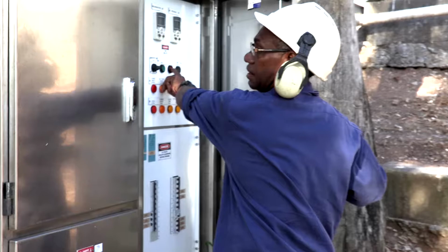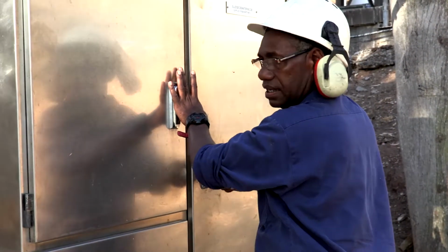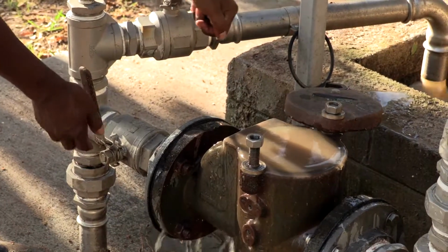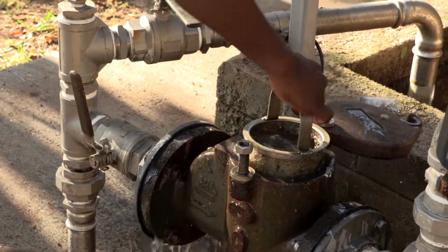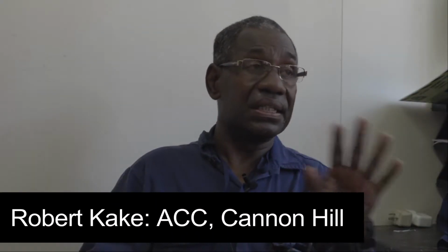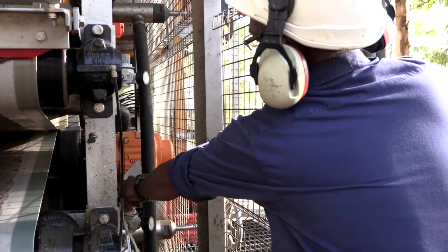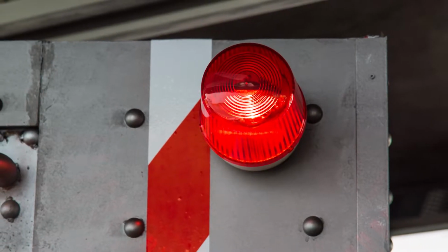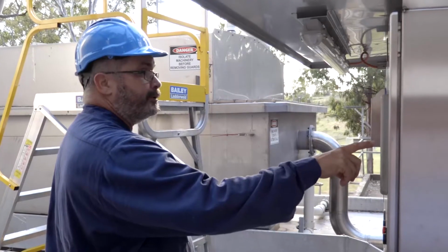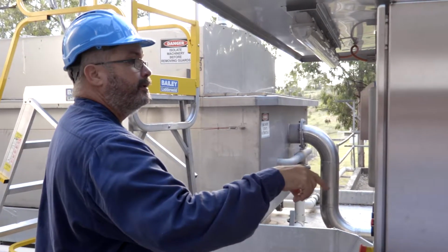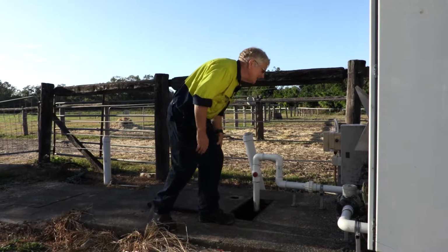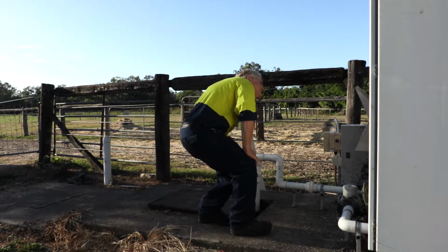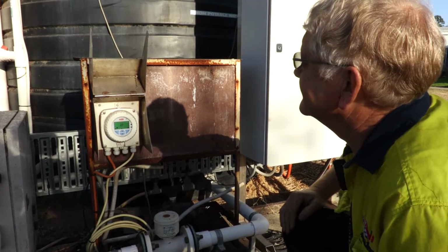In particular, operators need to watch out for overflows, blockages, especially of inlet pipes and screens, or equipment failures such as pumps. Blockage is easy to find out because you can see that nothing is coming, you know it's blocked. The pump, you only see that. But the system I'm operating is good because they've got alarms to let you know that it's close to overflow. Operators should also check that monitoring equipment, such as flow meters, are functioning properly. If breakdowns or malfunctions do occur, maintenance should be notified.